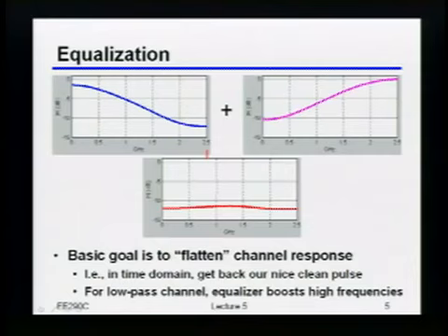Okay? So in general, if you have, let's say, a low pass channel, and you take that through something that looks like a high pass, quote unquote, equalizer, then at the end, you'll get something that hopefully looks quote-unquote flat. So that's really the name of the game with equalization. It's just trying to take those pulses that got messed up because of the frequency response of our channel and bring them back to being nice, clean pulses.